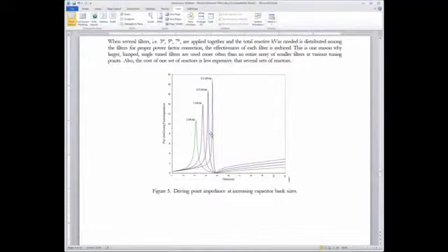When you blow one of the cans, you're going to shift everything to the right. And so one of the key points for notch harmonic filter design is making sure it's broad enough so that when this resonant point or the filter point shifts a little higher, like maybe to 5.1 or something, where this point moves does not get into a bad area. So obviously we could shift even up to the 6th harmonic or so, or 7th, and this first parallel resonant point is not going to sit on the 5th, and that's a good thing. The smaller the bank size, the more you risk that being an issue.